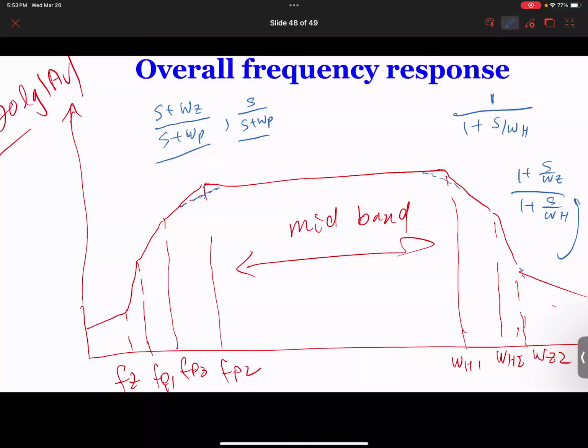But if your frequency is low, you don't have to worry about it. You can pretty much pick any device. The price difference can go from anywhere like 20 cents for a device, or you can spend $200 to buy a single device for very high-end application, for military application, for example, with very high common mode rejection ratio and very high frequency in the gigahertz range. So that's the high frequency part.